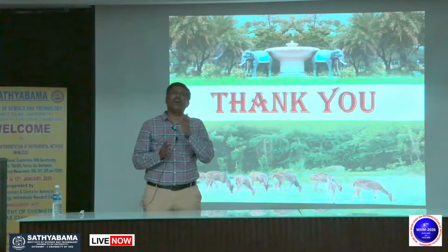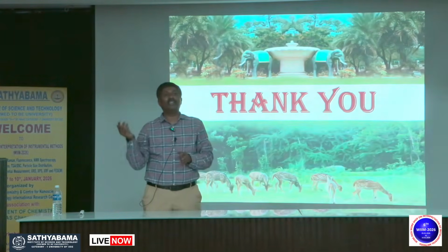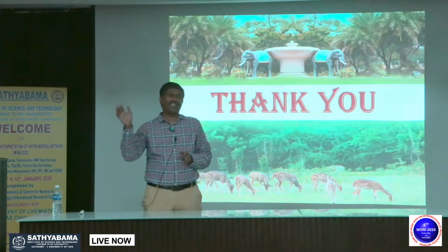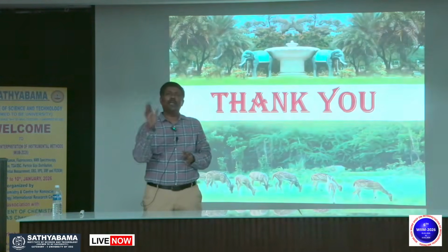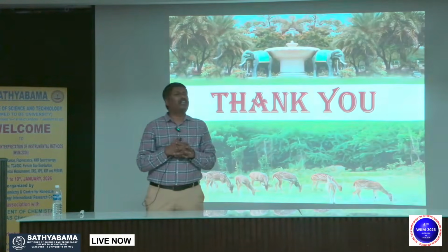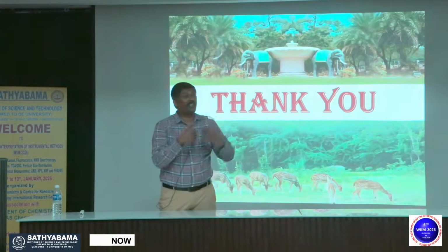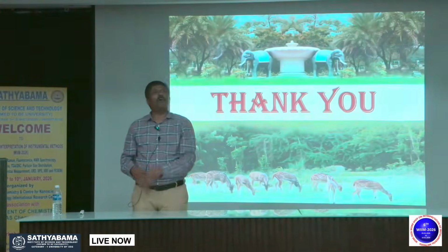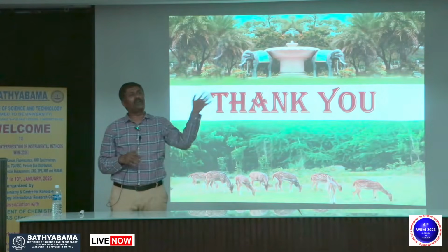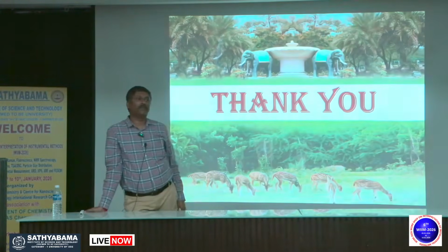5 degrees Celsius per minute is mostly acceptable. But if you do not have time, people go 10 degrees Celsius per minute. Only for PG experimentation we go 20 degrees. Otherwise, it is not at all recommended. 10 degrees gives a rough idea. 5 degrees is what most people use in literature and research articles. But if your research itself is on thermodynamics and thermal analysis, then people go even down to 0.1. 5 degrees is largely good. Most people, except for research articles, use 5 degrees Celsius.